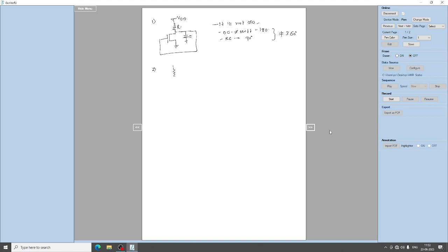We will take another circuit, where we add another stage of common source amplifier, and we have two stages of R and C, and this is the feedback. What happens here? From input to here you get 180 degrees, and from here to here you get an additional 180 degrees. So your DC phase shift itself is 360 degrees. If the DC phase shift is 360 degrees, then it will latch up.